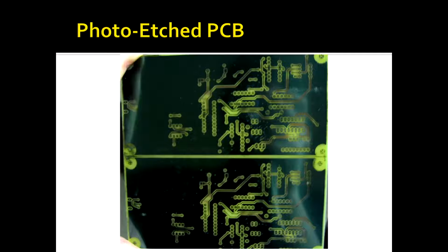So then I thought I'd make an even more feature-rich board, and because I'm thrifty, decided to etch it myself, which was pretty much an epic failure. What happened was my transparency, that you shine the fluorescent light through with your mask of the layout, was slightly off the surface of the board, which had the effect of making the artwork out of focus.